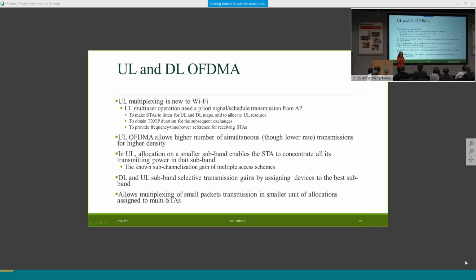On power imbalance. Usually an access point, for example a Wi-Fi access point, transmits at 18 dBm or 22 dBm. Wi-Fi is an unlicensed band, and the regulatory domain has hard limits on the max transmit power. It's like 2.4 gigahertz and 30-something dBm in the US, much higher than other regulatory domains. But usually an access point transmits 23 dBm. If our cell phone transmitted at 23 dBm, it would drain the battery very soon. So cell phones usually use 14 dBm for transmission. So this is the power imbalance. The access point also has more antennas and higher antenna gain, so this becomes a link budget issue as well.